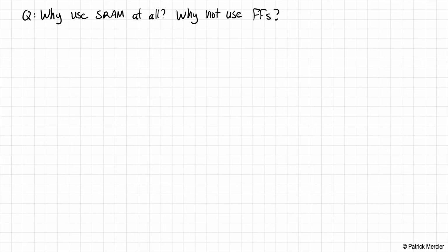We studied flip-flops, and although they were perhaps a little confusing at first, now that we understand them a little bit better, they're actually pretty easy to understand. They work fine. We don't have to have this weird small signal sensing. We don't have to have row and column decoders and so on. We've added a lot of complexity to our memory elements here. Flip-flops store memory perfectly well, in fact, using the same mechanisms as SRAMs do. So why don't we just use flip-flops?